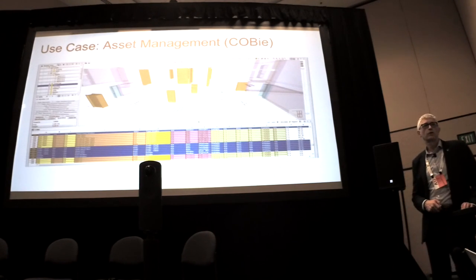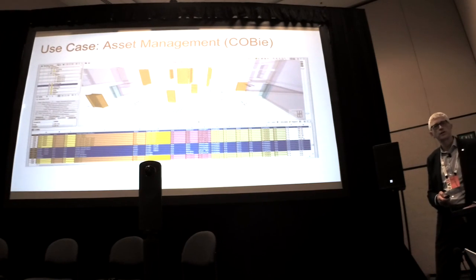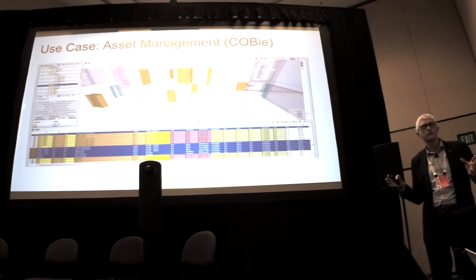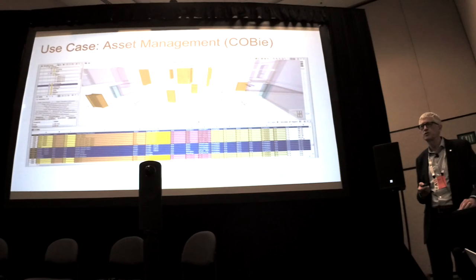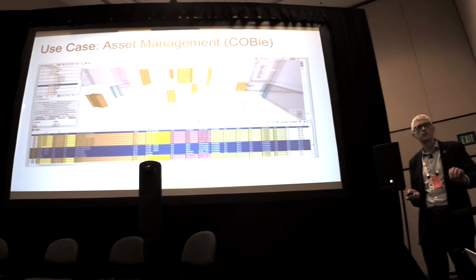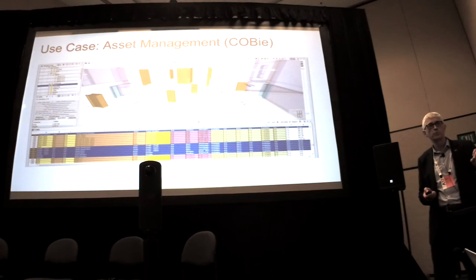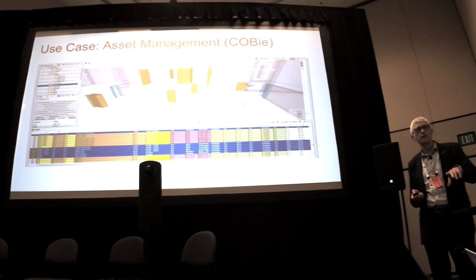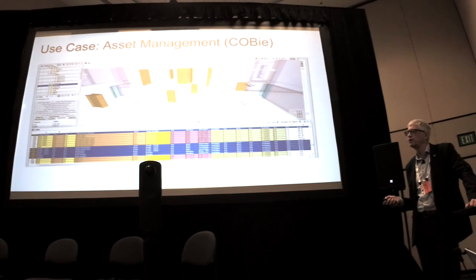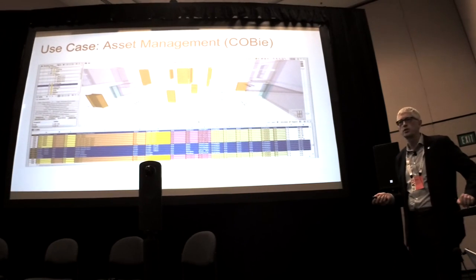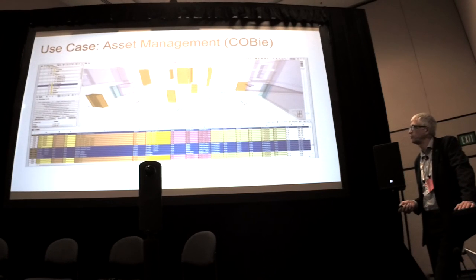And we've all tried to work with COBE. We're going to talk, if we have time, a little bit more about COBE after we do a test case here. But COBE is just a big way of looking at the IFC model sorted out into a spreadsheet and telling you what's everything you might need to exchange. What it really needs to have is for any particular use case, like if it's for asset management or facility or for equipment maintenance, you need to say which of those classes of data do you need to meet your requirement. And I think that's where we haven't gotten as far with COBE as we need to have the exchange requirements documented to make that process easier. But maybe we'll talk a little more about that.